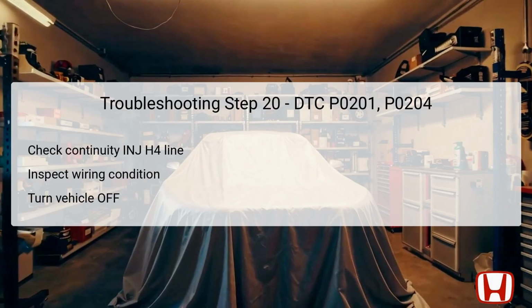At Step 20, the task is to check the continuity of the INJH4 line. You should disconnect the number 4 injector connector and ensure the vehicle is off while measuring between the specified test points. Confirming continuity indicates a functioning wire.